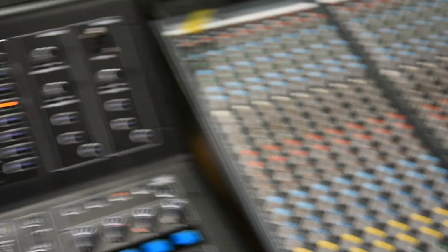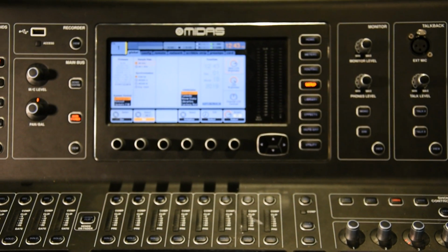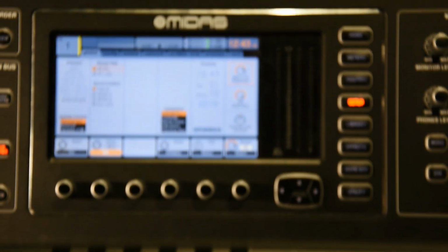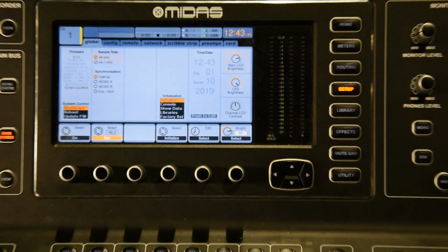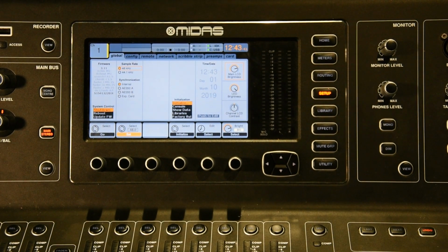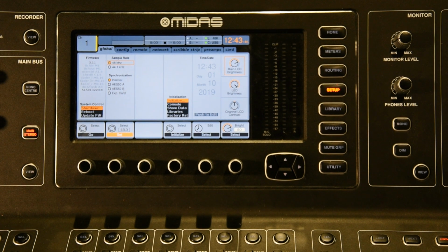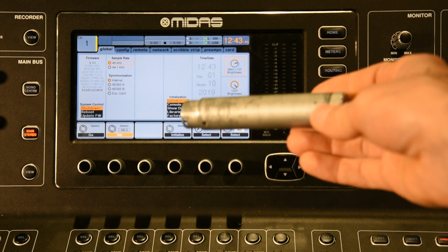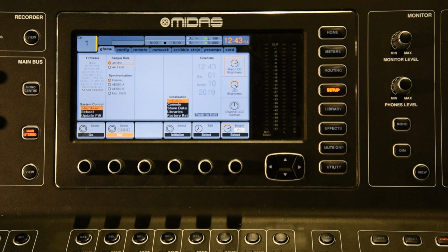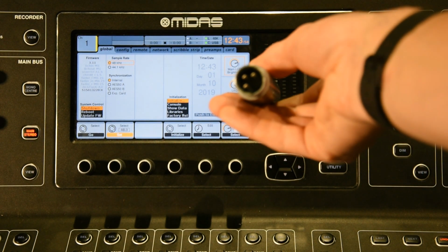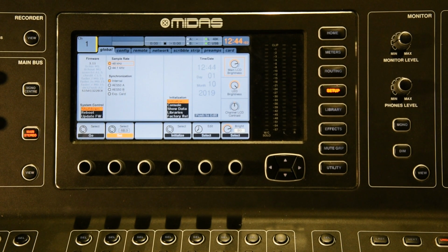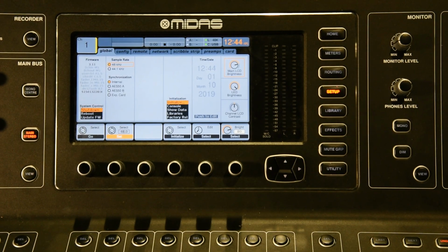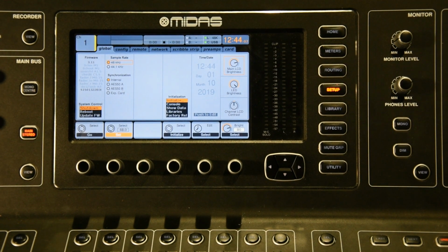So when you've done that on the M32, the next thing to do is get the signal generator ready so you can send some test signal out to the monitor system. It is possible to do that with a device called the pink stick. There's a pink stick that outputs pink noise, and it's XLR, so you can plug it into a snake or stage input. But in this case, let's use the signal generator because you might not have a pink stick. So, signal generator goes like this.